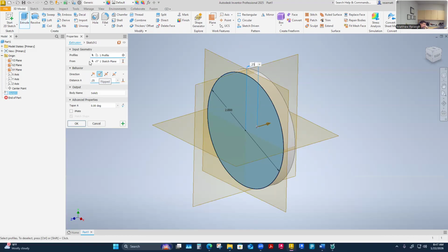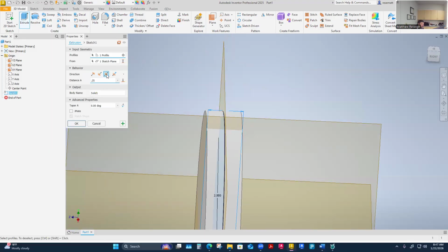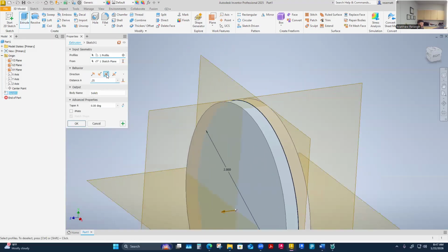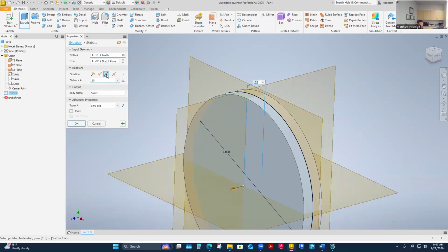You'll see me probably starting next week to do a few more symmetric extrusions, and the reason why is because it'll put my plane in the middle of my part. What you'll learn next week when we start building assemblies is that sometimes I strategically use the preloaded geometry in my part, which I feel like are the axes, the planes, and the origin point, to constrain parts together in an assembly, because that geometry already exists in all parts.